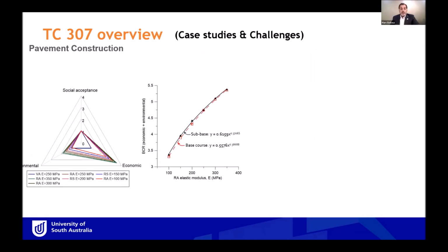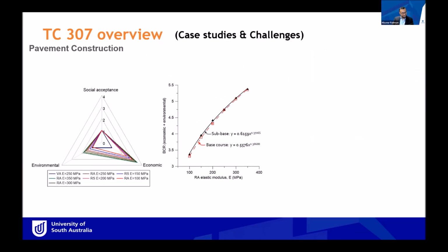Yes, the three circles are playing together. Now over here, what I'm looking at is the benefit. So social benefit, if you are constructing the pavement, the appearance would be exactly the same if we use recycled material or virgin material. So we assume in this case, the social index remains the same. But what happens, the environmental benefit in terms of carbon emission and the cost, the benefit increases. And that increase will depend on the quality of subgrade material we achieve through the recycled material.